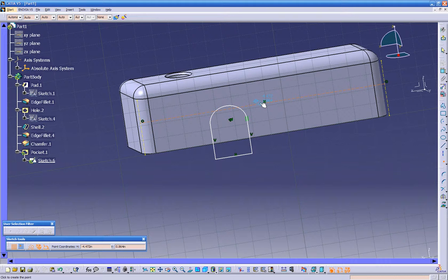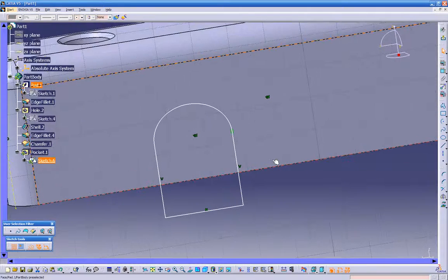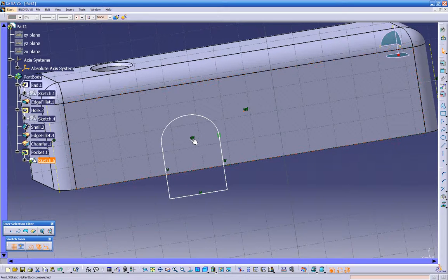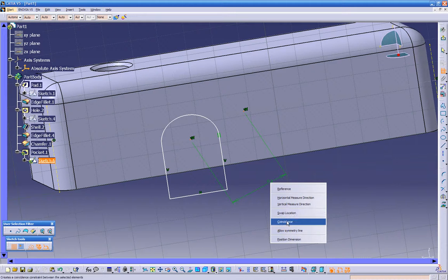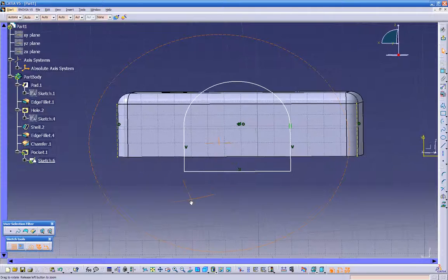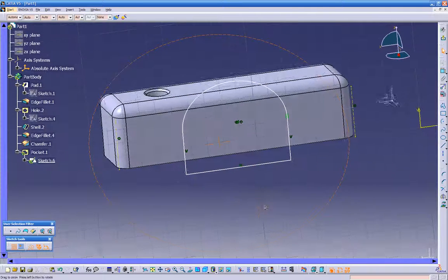So we get the full moon, that means we're in the middle of the line. Click OK. And let's pre-select this point. We got 2 points pre-selected, and let's go to constraint. And before you click, let's do a right click and then coincidence. And we got our part in the center.